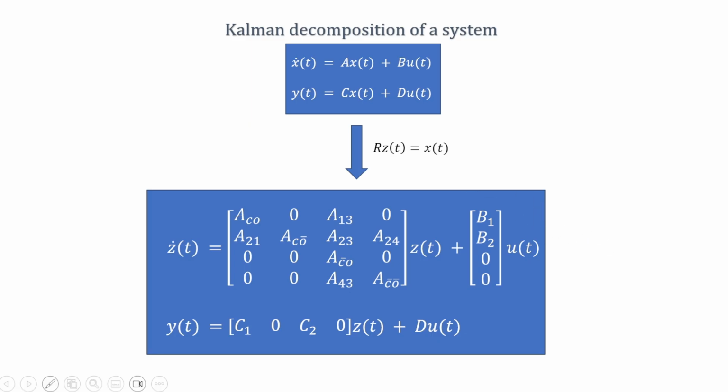You can always come up with an R matrix by which if you transform, the system will look something like this. And notice in this system, if I draw the blocks, you see this part corresponds to the controllable part. You can consider this to be a B bar. So you can see that this is in this form A_C, A bar 0, A_UC and B bar 0 form.